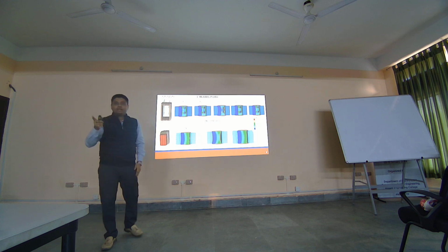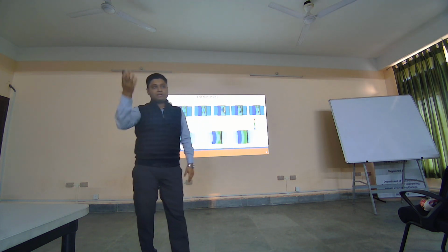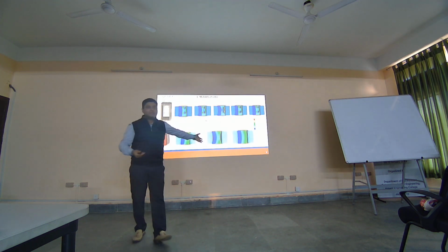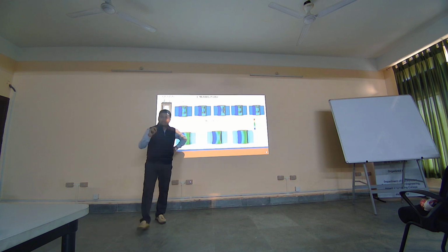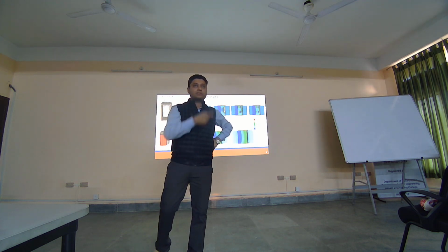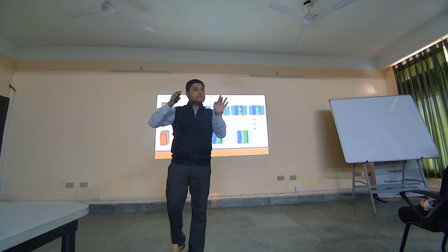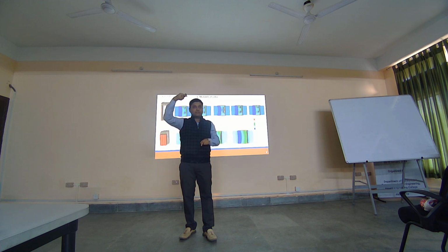Another point which we thought, and I think it would be very applicable, even you can pursue this. This is an open problem, so we do not restrict things like this. If you wish to take it up, you can take it up. Another thing is, you have corner effects in this kind of sharp structures. In gate all around structures, since towards the side you have two gates, at the point you have very high electric fields, and it degrades the oxide dielectric in that particular region, and also the semiconductor there, right?